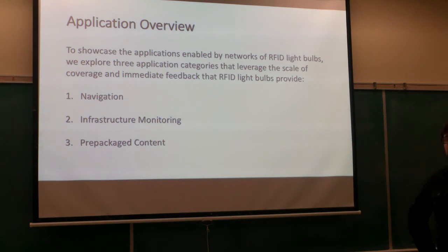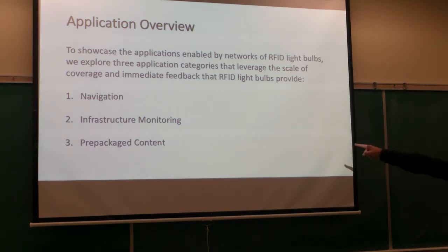So the second was infrastructure monitoring. All of the tag sensors that I mentioned in the previous slide can be used to monitor the state of our homes, right? So when is our heating system on? You can figure that out with the thermostat tag. You can figure out what temperature a room is with the temperature tag. You can figure out things related to energy efficiency of a home if you instrument windows and doors with some of the contact switches, right? You could do that